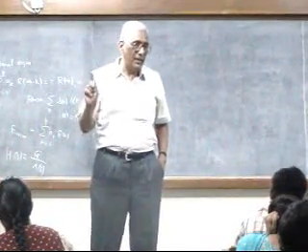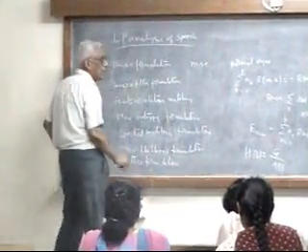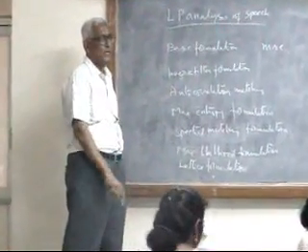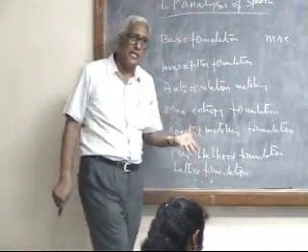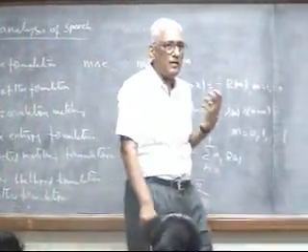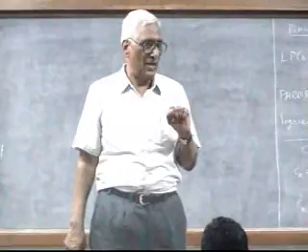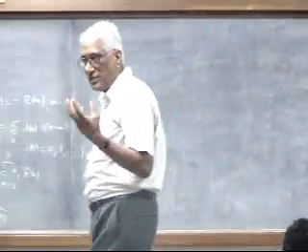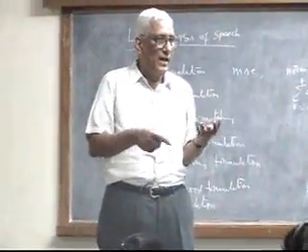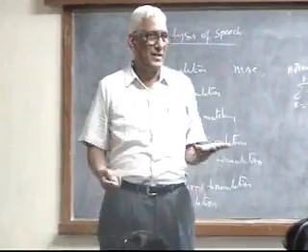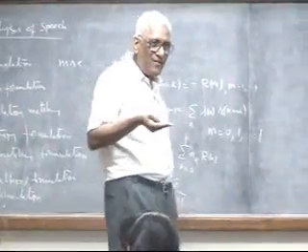Get the point? And also what we have noticed here, and it's very interesting and important, is why linear prediction has become so popular in speech as opposed to many other domains: it tries to approximate the peaks better than the valleys. There is a bias towards approximating the peaks than the valleys, and it is better that way for the simple reason that the valley in a spectrum as a function of omega is more vulnerable to noise. If there is some constant background noise, you can see that it is the valley that gets affected first, before the peak.